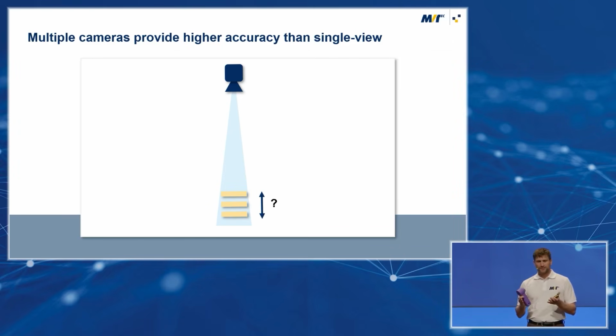So we could find this object quite well and accurate in X and Y, but the Z-axis is very difficult because maybe we have round curves that are not easy to detect, or also we have variation in our product because they are manufactured differently, like maybe a 3D printer in this case with a bad quality, or another like a milling machine. Some parts have variations. So we are in trouble sometimes.